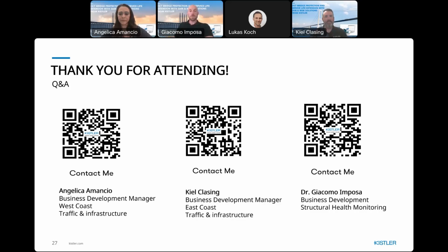Certainly, I think that is an interesting question. Since we are experts in dynamic measurements, we can provide different types of sensors for these purposes. Obviously, the main core is made by the K-Beam MEMS capacitive accelerometers, but we also have different types of accelerometers like the HEPI, and in our portfolio we have different sensors for other purposes, like dynamic strain gauges and acoustic emission. Since the topic of SHM, as I showed you, involves a lot of parameters, for sure we can integrate other third-party sensors correlated with the specific needs of the customer and the specific needs of the bridge.